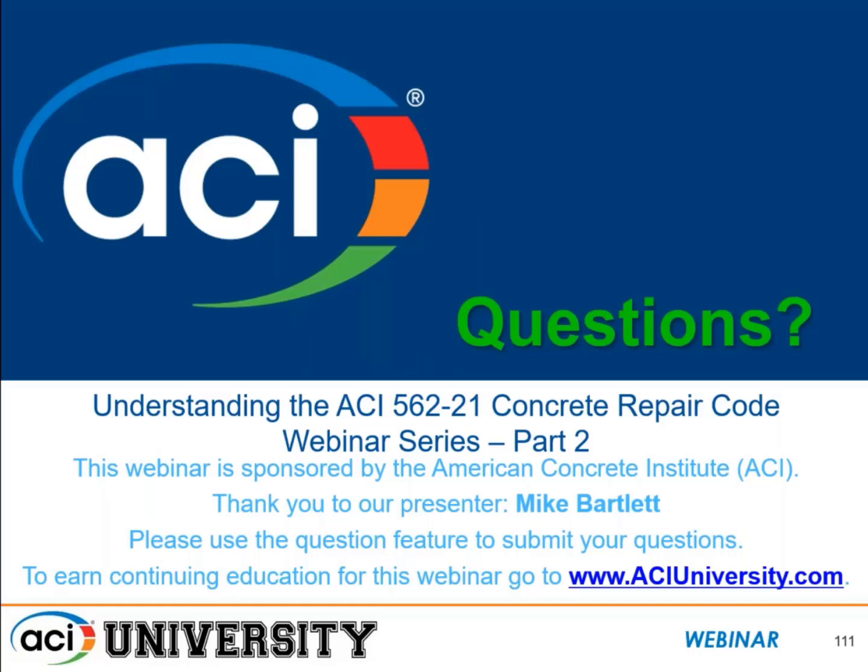And so I'm pretty sure 214.4 recommends that if you're using smaller cores, that you try to establish a correlation between the small core that you're using and a larger, more conventional core for the concrete that you're actually working with. So 562 doesn't specify a minimum core size, but it does say that the provisions that it provides only apply when you've got tests of 4-inch or 6-inch diameter cores.